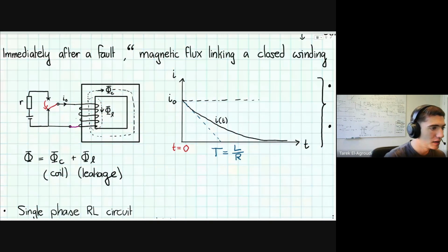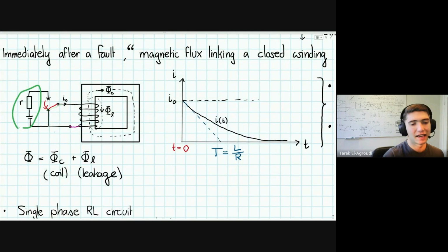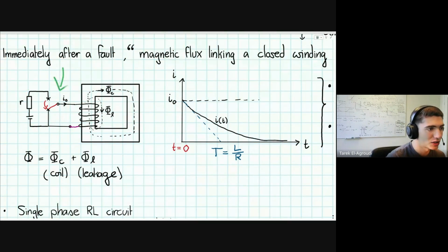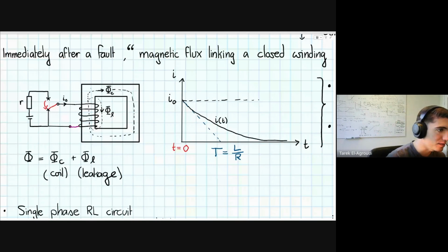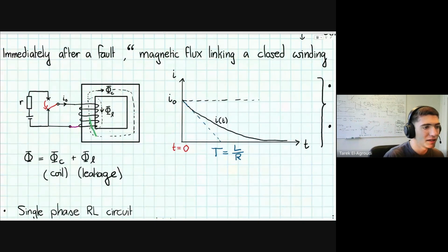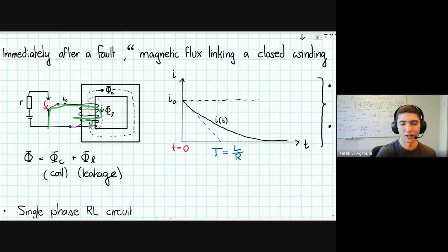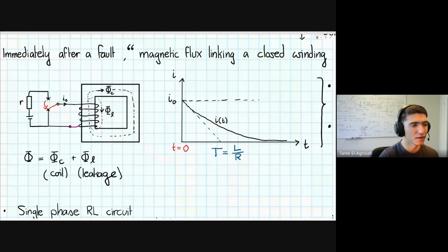If you kill the connection to the voltage source, the analog in power generation is that there's a three-phase short circuit on the generator terminal after the transformer. So you lose the grid voltage. Well, initially technically there's no voltage source anymore. This is just a wire, so there's no voltage, there's no current.